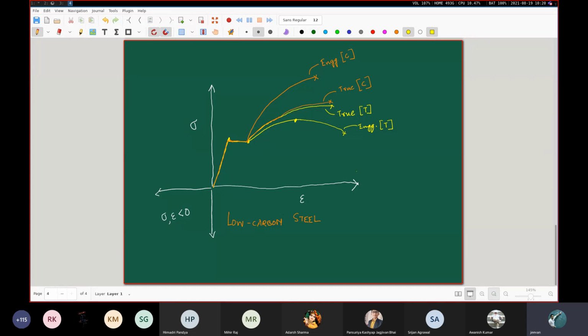For the engineering stress, engineering strain diagram in the tensile case, you have a certain area, and that area is the original area, the undeformed area. Even though in reality the area is decreasing, so you will have the slender specimen which was initially like this. After deformation, it elongates, and slowly in the middle region it becomes thinner. So what actually happens is that the area is decreasing.